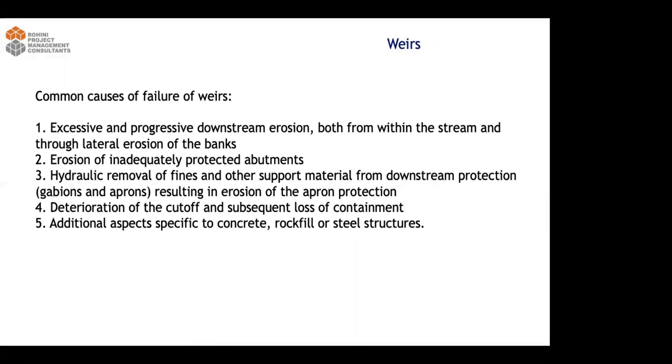Excessive and progressive downstream erosion, both in-stream and lateral erosion of the banks, erosion of inadequately protected abutments, hydraulic removal of fines and other support material from downstream protection, then deterioration of the cutoff and subsequent loss of containment, and additional aspects specific to concrete, rock fill, or steel structures, right?